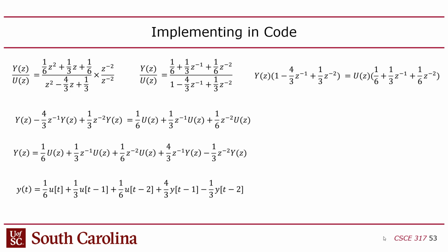So I was able to put this in a form where I didn't have to have a lot of memory. I only had to look back. I only had to have shift registers that took me back 2 samples into the past, and yet I was still able to execute a model of a physics model that had an integral in it. I think that's pretty cool.